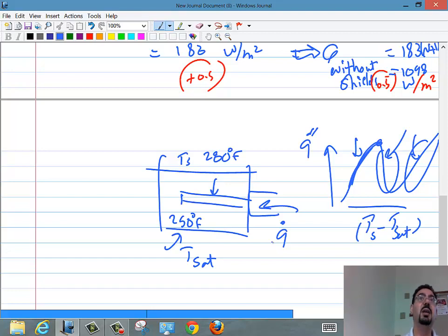After a few seconds, the water will be at 75, at 80, at 90. The 1,000 still needs to get out. Because it's still natural convection, it's not enough to be at 100 to disperse this 1,000 into 90 degree Fahrenheit water. So as the water temperature goes up, the TS also goes up.